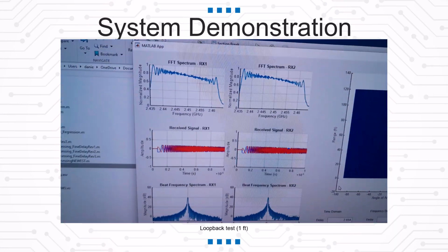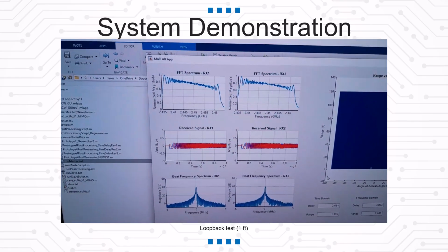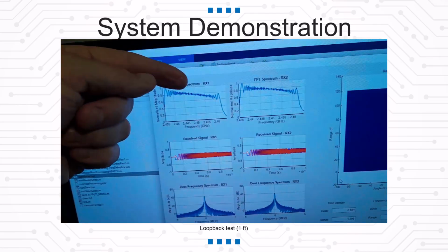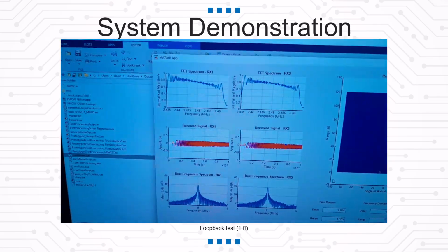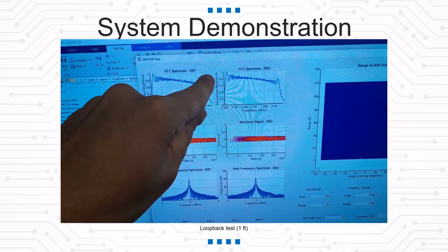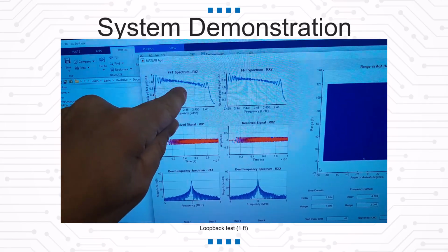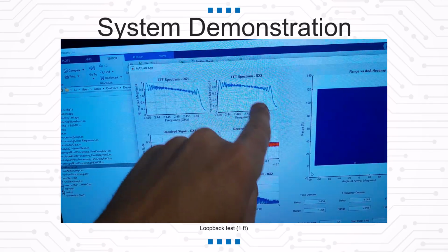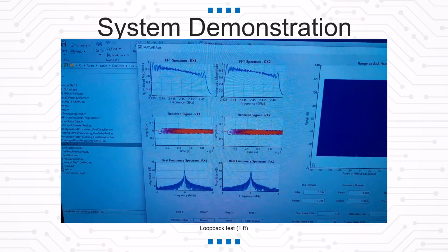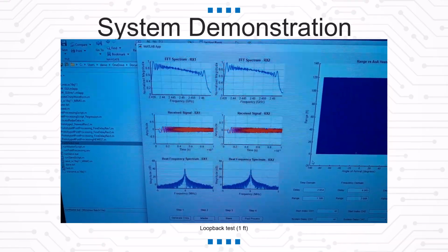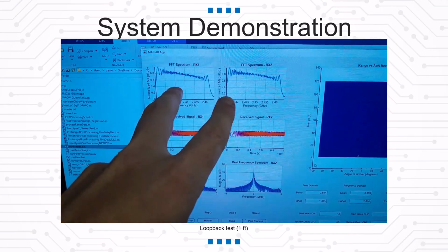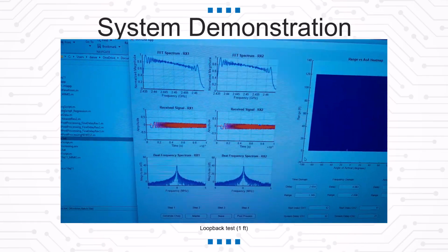Okay, so what I see are two FFTs. We can see that there's slight attenuation on the higher frequencies, but both of them have similar results. I've noticed with this system occasionally one of them will have really good results and no attenuation, and when that happens the other one will just completely destroy the upper end. So it seems like a lot of times there's a dependent channel, but if they can align up like this, that's the best.